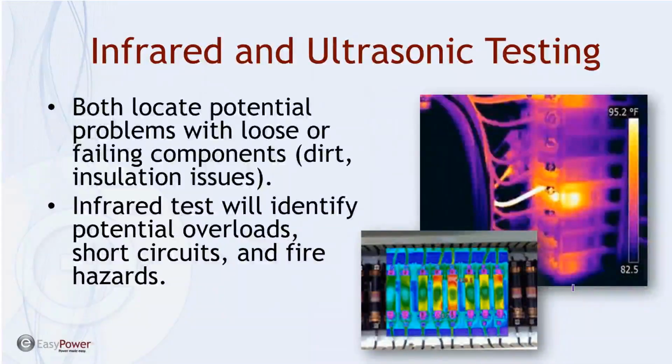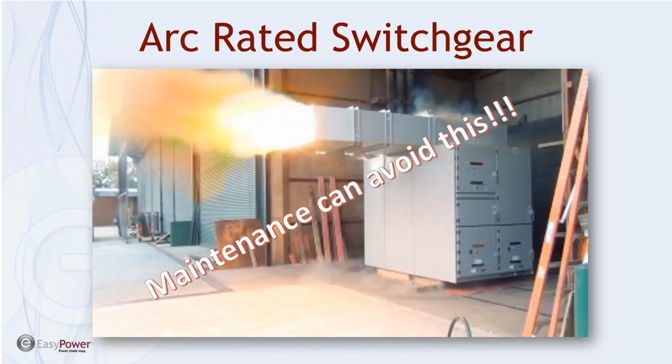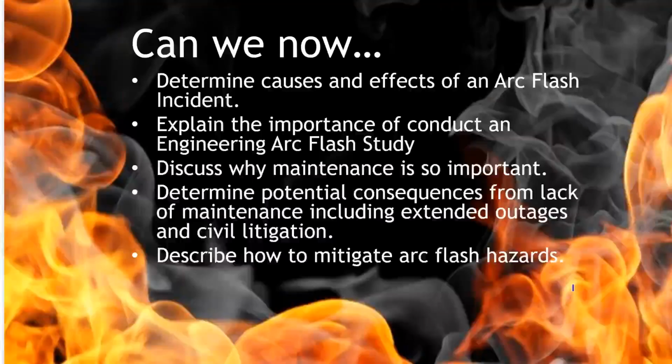Infrared analysis is always good as a proactive approach rather than a reactive one. Arc flash rated equipment is a good thing also. It's very expensive, pricey, and very heavy, so it's not something that you see very often in the area.